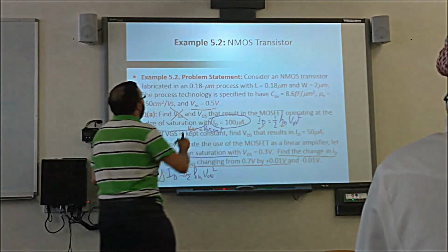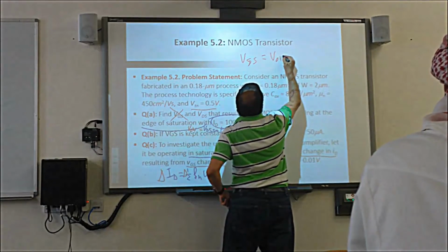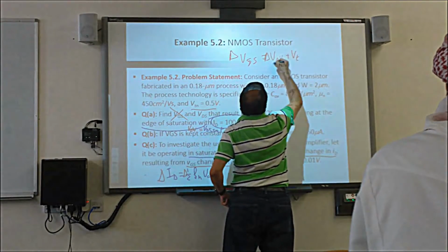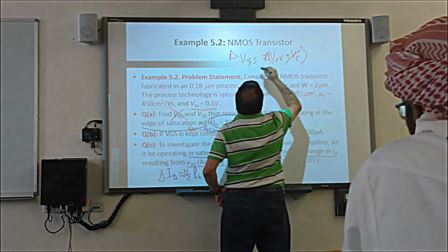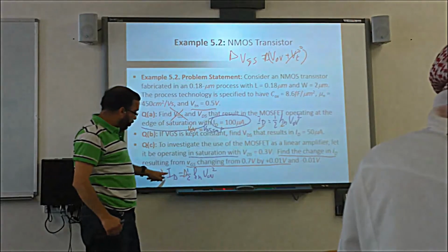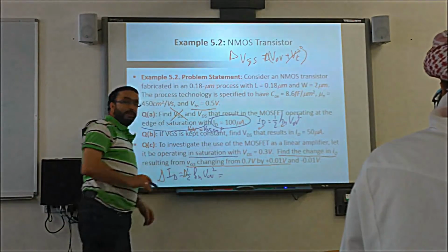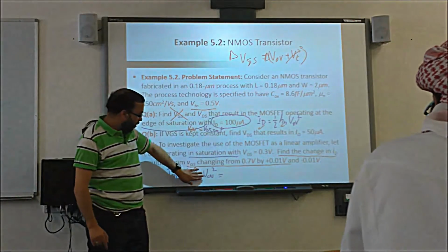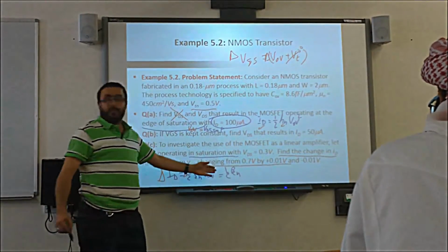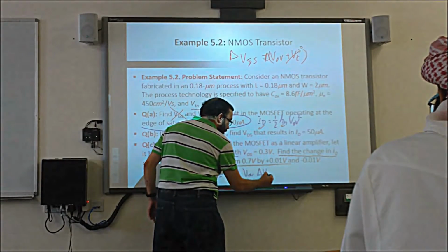So first of all, remember that VGS is equal to overdrive plus VT, yes or no? So if I take delta here and delta here, the VT term goes to zero, and delta overdrive is the same as delta VGS, so I can replace here. This is math. Today you can enjoy math. This is constant, let's get it out: half Kn, and delta of V overdrive squared is equal to V overdrive, delta V overdrive.